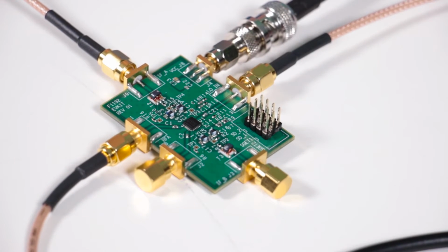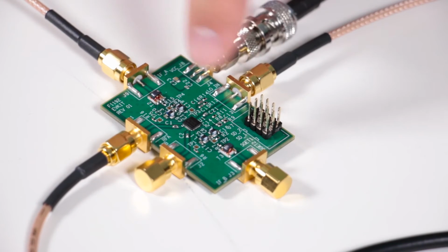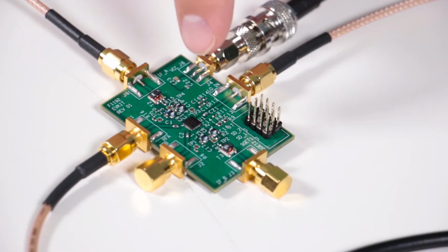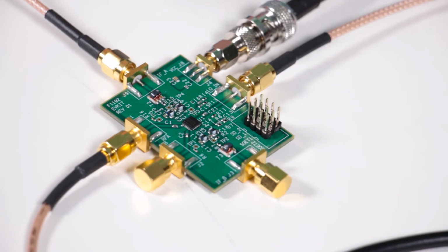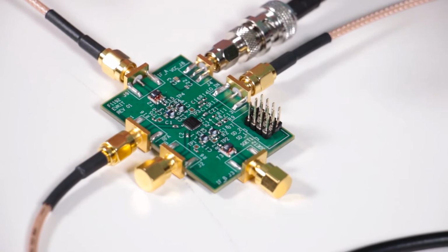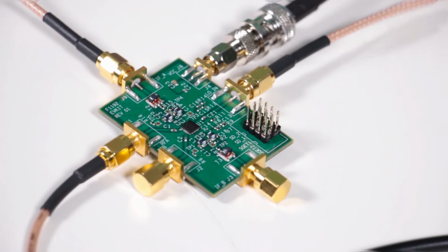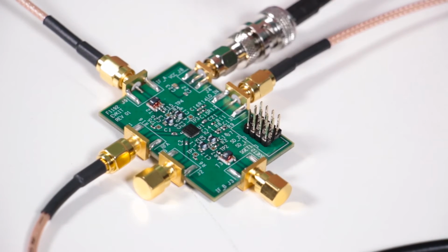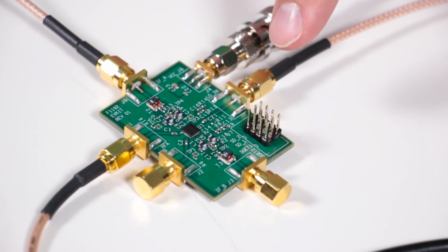And since we're using test equipment, we have these 4-to-1 baluns. Normally the IF is a 200 ohm differential output for driving things like pre-ADC filters and keeping distortion very low. But again, since we're using test equipment here for evaluation purposes, we have a 4-to-1 balun to bring that down to 50 ohms. These headers over here are for setting the gain as well as disabling individual channels.